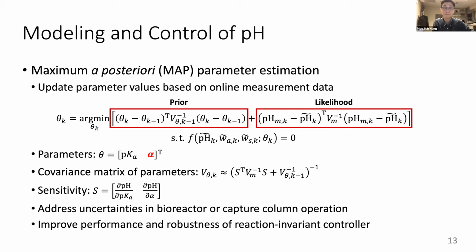Cool, thanks. Do you have a regulatory PID box? Well, I guess, are you just using on-off control for the pumps? No, actually it is a PI control, and how we implement it in the PLC controller is we just use math boxes to have this error term and the integrator term, then calculate what the control input is going to be and give the actual control input value to the pump through the connection between the PLC and the pump.